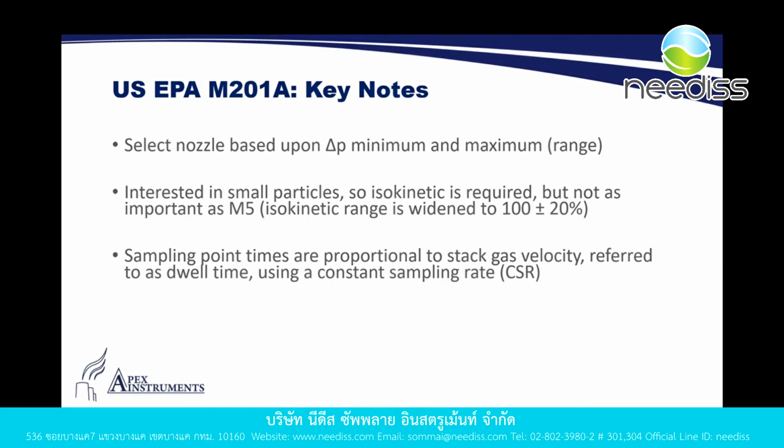Now, as a point to that as well, sampling point times are not necessarily considered isokinetic, but they are considered proportional to the stack velocity.